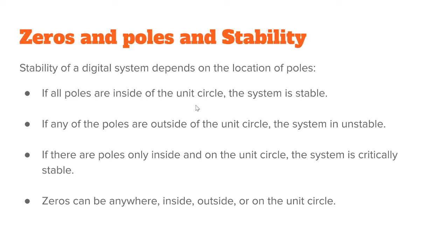If it's unstable, meaning you have even one pole outside the unit circle, then it's guaranteed that it will at some point cause overflow in the calculations. No doubt about it. It happens eventually. So stability is a good property. Critically stable systems in the digital domain are even more critical than in the analog domain.